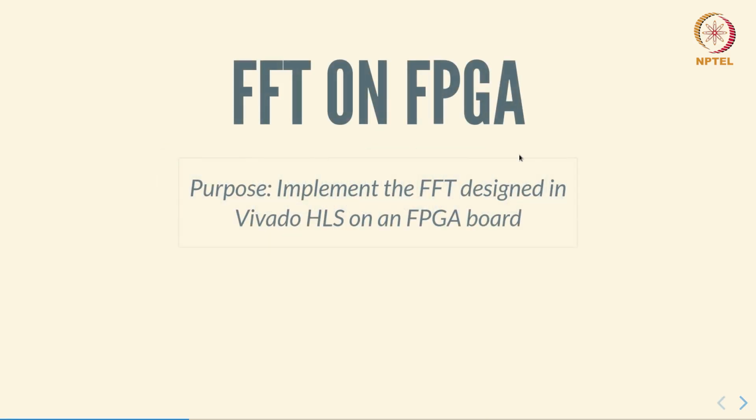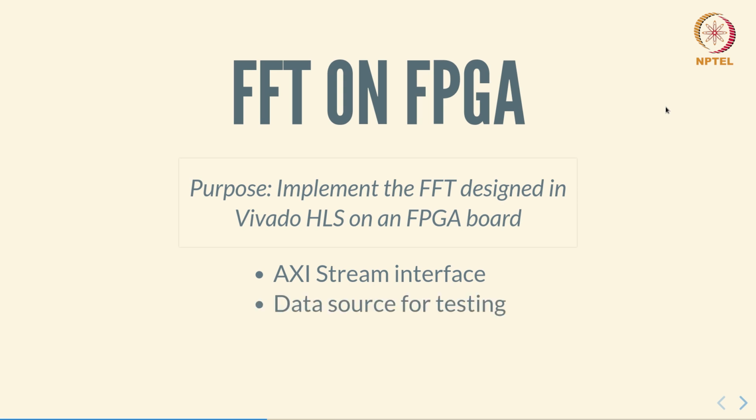In this video, we are going to implement the FFT that was earlier designed in Vivado HLS on an FPGA evaluation board. I'll first briefly discuss the Axis Stream interface which we use to pump data into the FFT module and also to get data out of it.